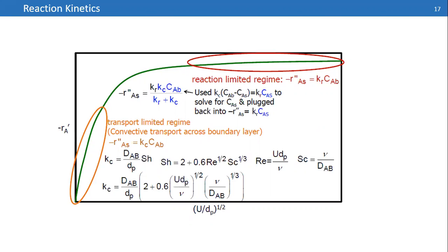Here I have a question. I'm developing a kinetic model inside the lab, and I'm going to apply that inside COMSOL. Does it make sense? I'm scaling up our system, so I'm increasing the size of the particle in the industrial sector. What would be the problem? The answer is that when you are applying these changes, you should take care of your kinetic study. Your kinetic should be intrinsic, otherwise you cannot use it. It's limited to a specific condition.